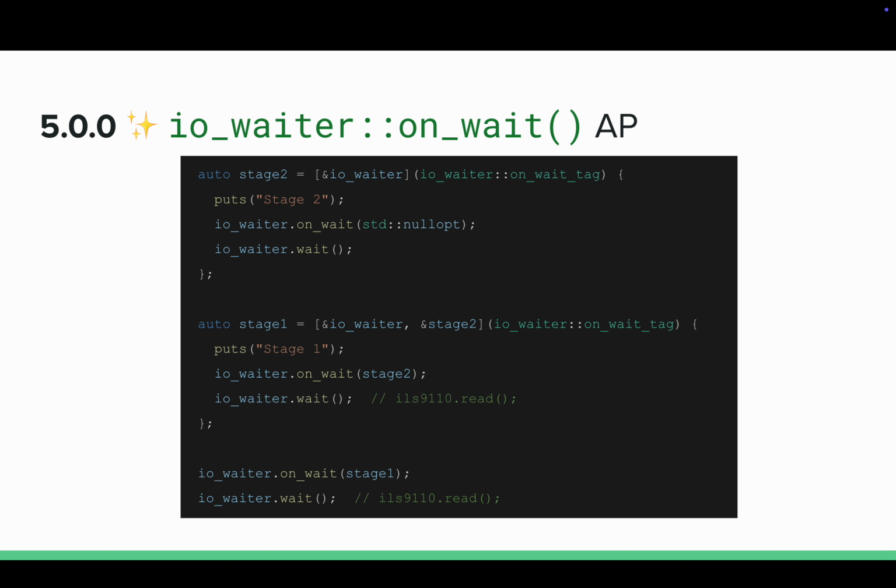But this will require us to have a couple of threads for each one of those if we wanted to use the normal I/O wait paradigm, which is to keep everything blocking: execute the transfer, then sleep that thread, go to the next one, do the transfer, sleep on the wait, next one, sleep on the wait, do it all until they're all finished, and then they'll all wake back up when they need to, give the data to whatever needs it. Another thread will aggregate it and shoot it off over serial. We could use FreeRTOS for all of that.